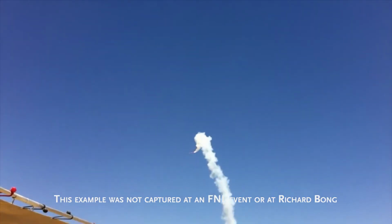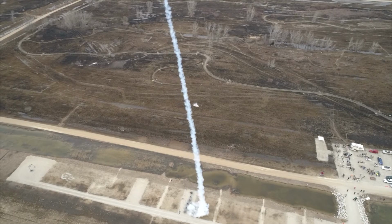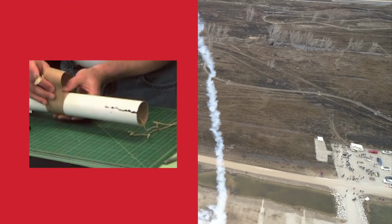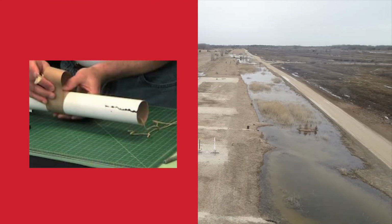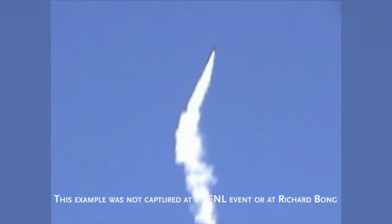Try and avoid errors like these. If the body tube ends are not strong enough or the Kevlar extends past the end of the tube, a zipper may occur, causing damage to the body tube. If the motor mount bonds are too weak, the motor may fire through the airframe.